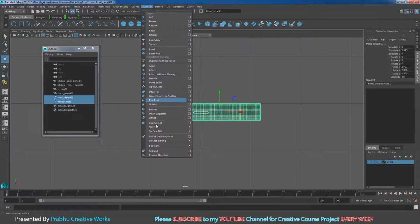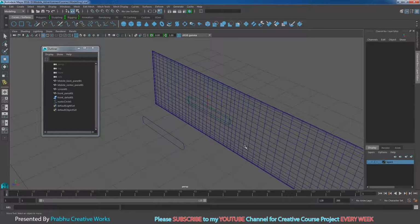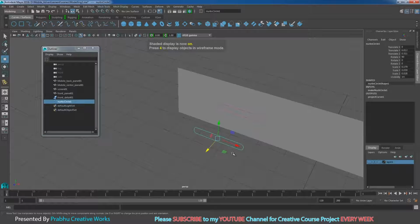Now I want to project this curve on that surface. Go to surfaces and choose project curves on surface. So that means your curve will be projected to your mesh. Press 5 on the keyboard. See here, when I select my node circle and move, the projection will be followed. So I will undo that one.